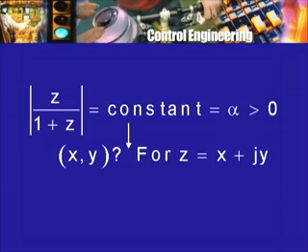Of course, the contour map shows you the actual height, or the equipotentials show you the actual potential, whereas here these M circles, if I can draw the whole set of them, would give me the value of the closed loop gain corresponding to a particular point in the complex plane, which may be the value of G(jω) for a specific G and a specific ω.